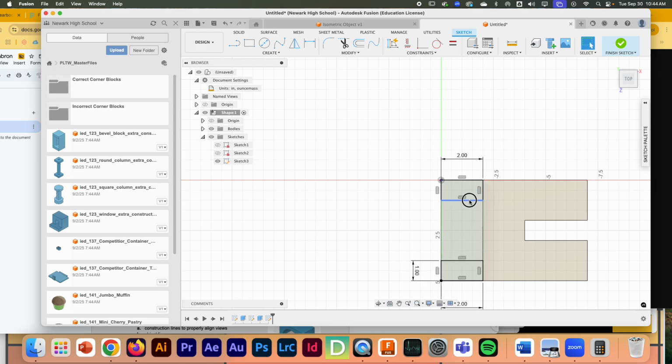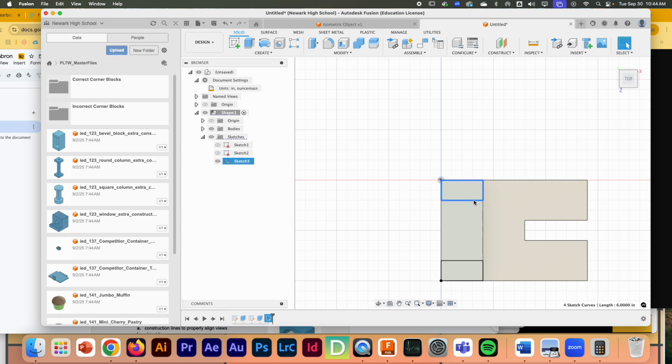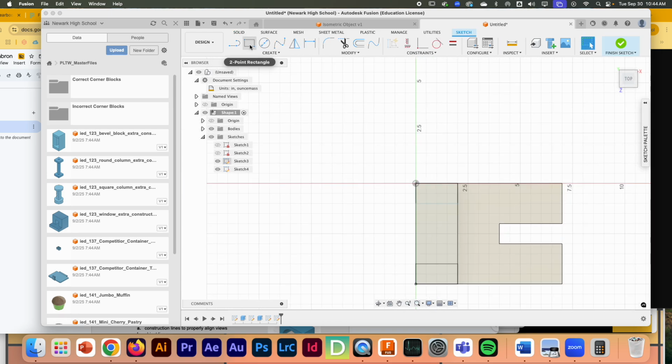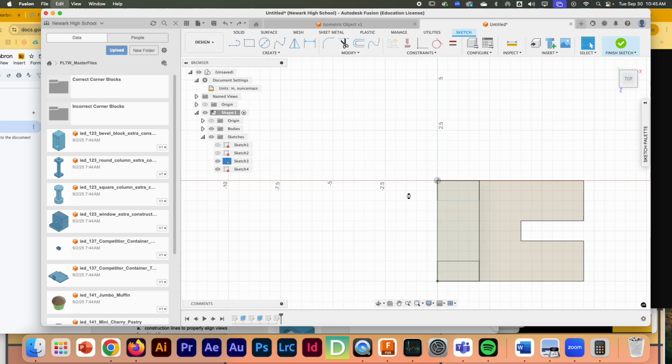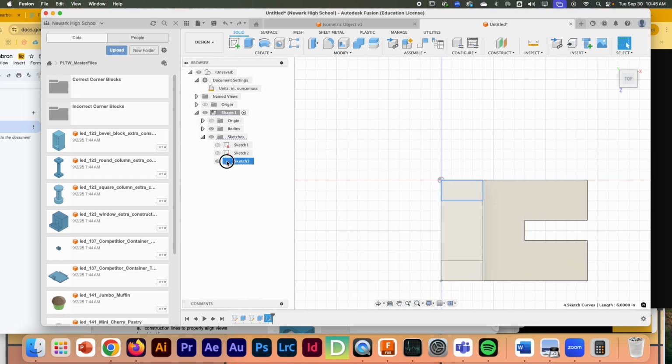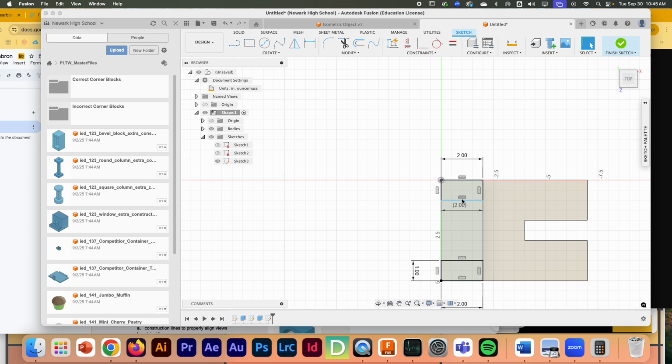We're all good there. I don't know why it's saying that's undimensioned. We can say that you're 2 inches as well. That's bizarre. What's going on with this sketch? Final thing I'll do here is go back into this sketch, and I can go in and define this middle box. Didn't like any of that. What's going on with this box? Is it just not defined? This is defined, this is not defined. So I'll dimension that and say that that is 1 inch.